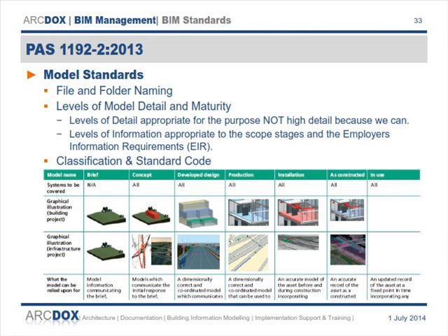That bit across the bottom is about 3 pages long. So there's like a column underneath each one of those which goes through and describes what actual LOD 3 contains, what it can be used for, what the model can be relied upon, which is quite important because not everything in the model will be to the same level of detail. So you have to define what the model can be used for and what the model can be relied upon.